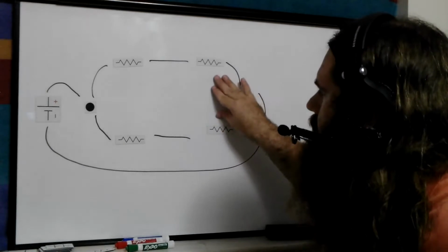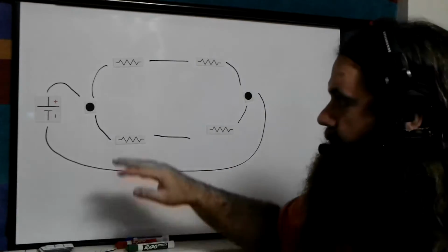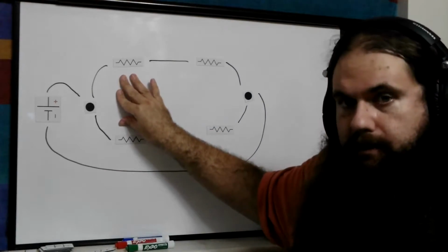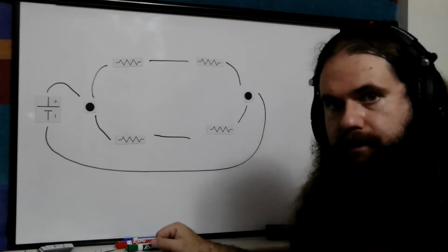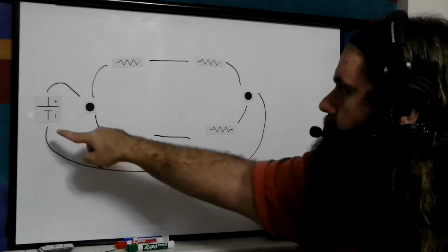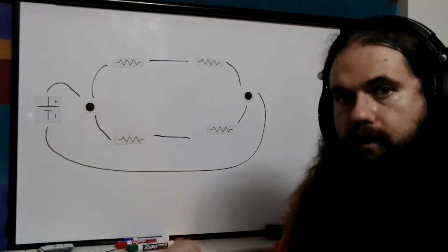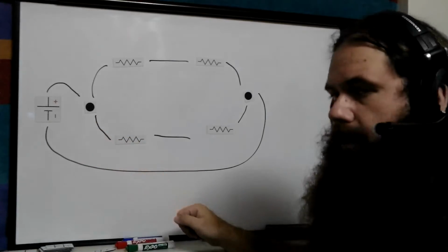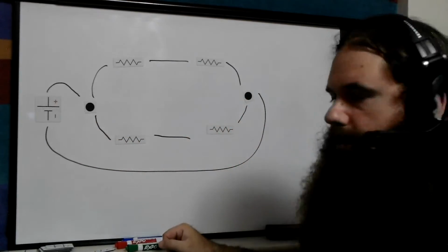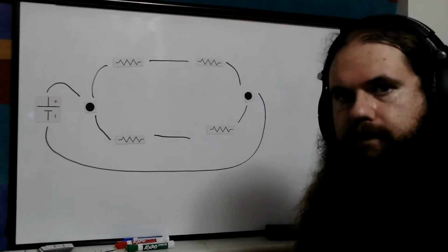So let's say, for whatever reason, you know the voltages across these 2 resistors and this one, then you need 2 equations because you have 2 unknowns. So you do that loop and you get 1 equation, this loop using different values, and you get another equation, and now you can just use algebra to find both of these voltages.